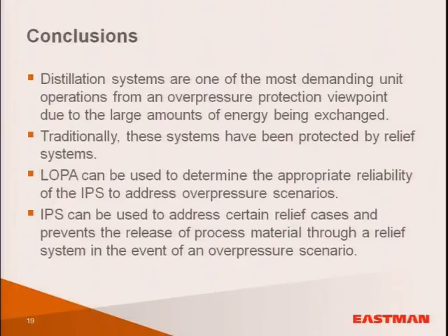And the reason we did that is because they were going to use 15 psig steam in certain applications, and they were going to use 125 psig steam in certain applications. But they really only needed like 30 psig steam. So we put in a pressure reducing valve in the steam supply and created our own 30 psig steam supply and followed that up with a relief valve. So we put a large relief valve in the steam supply. And that also would have given us the same type of protection that our SIL2 interlock would have.